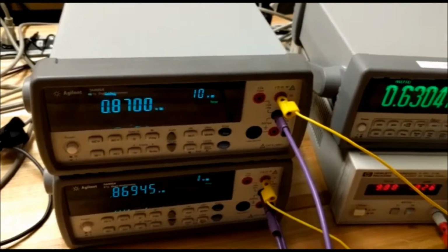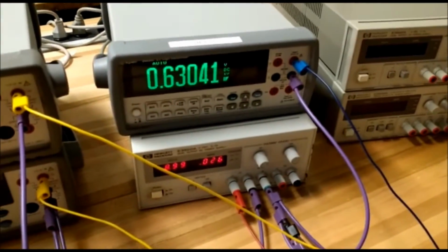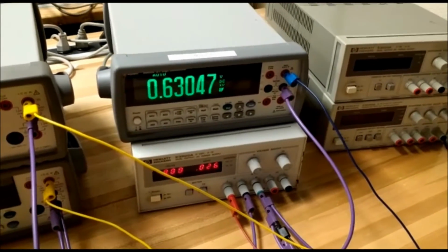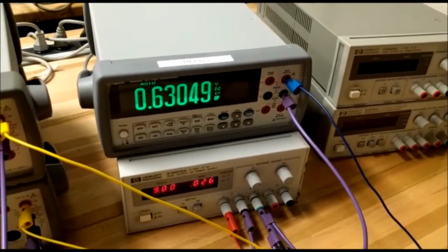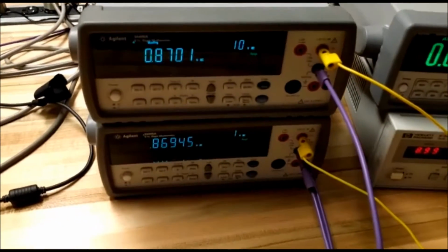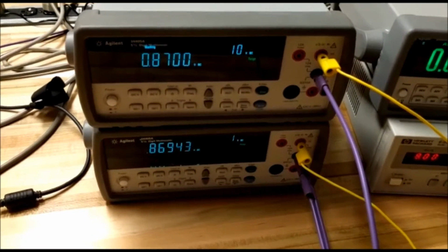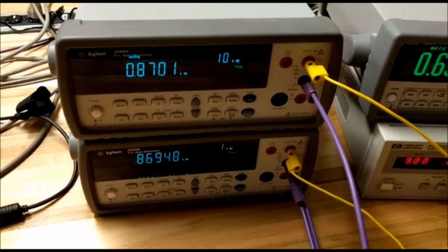So this explains that the accuracy of our BGR circuit is plus or minus 2 millivolts, with 0.632 volts as the output voltage at room temperature, and our error amplifier maintains the same voltages at both its inputs at all temperatures varying from minus 20 to 50 Celsius.